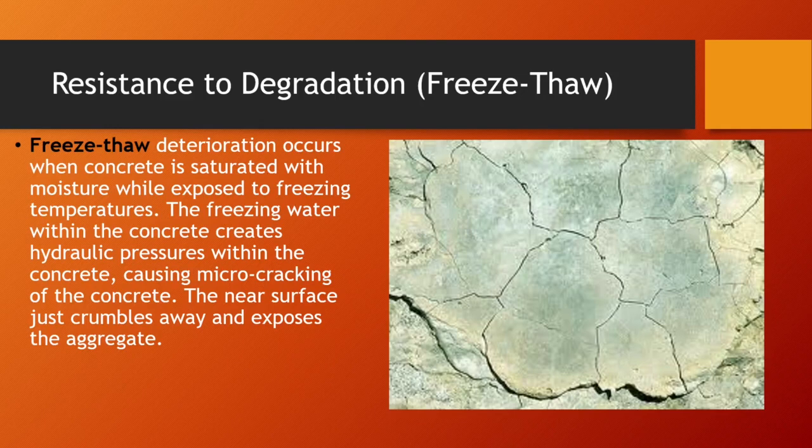But with air entrained concrete, typically that could be used as an access road to a farm where no connecting drainage is available, the air pockets are deliberate and they're big enough to hold water and drain away. So it's quite a good strategy where it's allowed to expand in these pockets and it's not going to cause too much issue. So that's when we use it to our advantage.